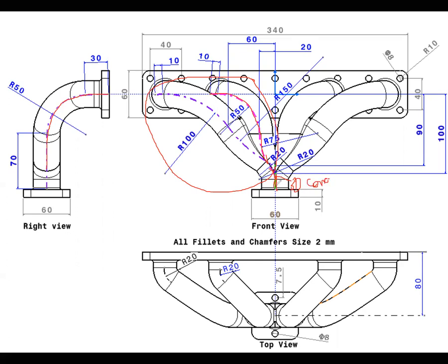This is a straight pipe. So a 3D folded pipe is connecting to the straight pipe, right? So we have to create a 3D corner with radius 20. And similarly here also there is a 3D fold connecting to a straight pipe, and here also we have to use a 3D corner. And we have to create lines, and also 3D fold. Those are the different tools we use.